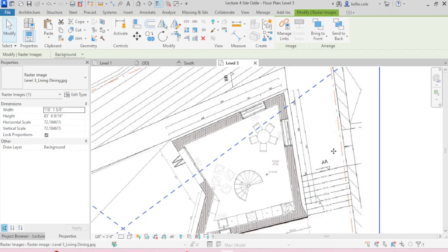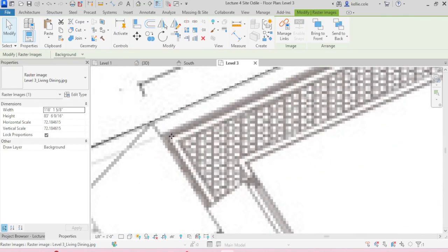The next form we create is one that is going to respect that perimeter wall of this plan. We're using the massing in-site type of modeling so that we can drag and align those walls in elevation and 3D form using the X, Y, and Z component tools in that command.